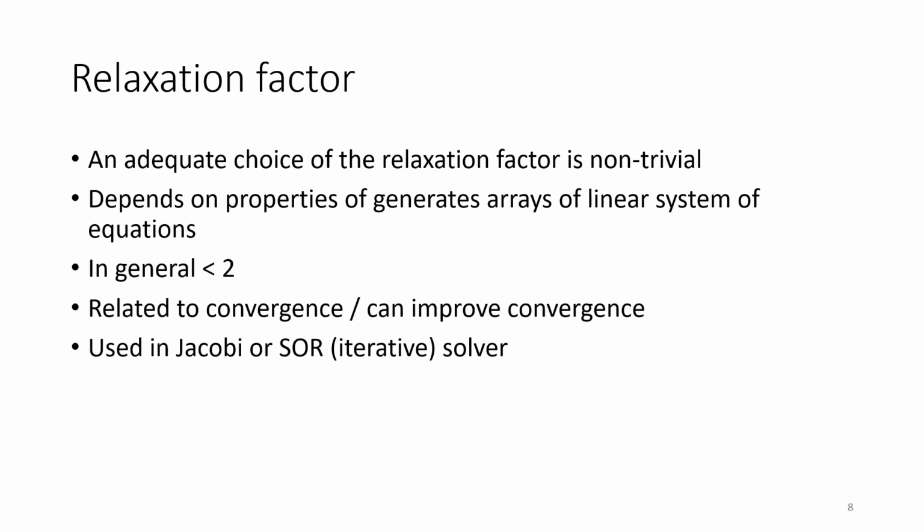There is, for the groundwater flow module, an input parameter called the relaxation factor. It is only relevant for two kinds of solvers, if you use the Jacobi or the SOR solver. This is really a non-trivial task. Estimating this kind of factor a priori is difficult. As a rule of thumb, it is usually smaller than 2. Personally, you can start with a guess of 0.5 or so.